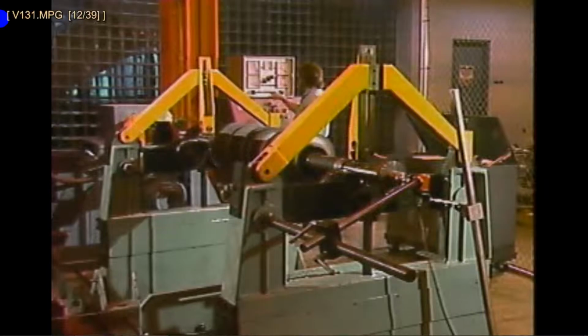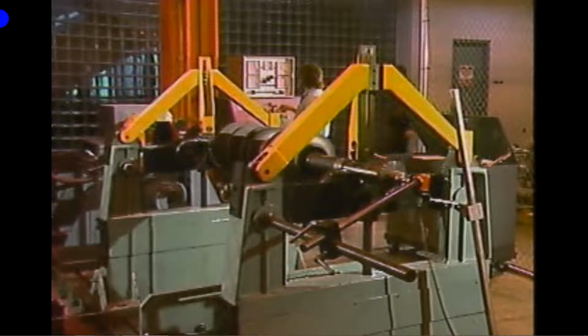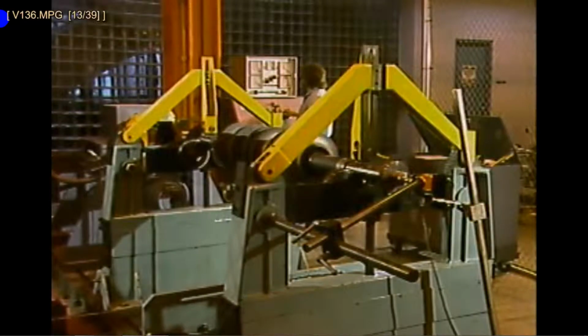One of the most common causes of vibration in rotating equipment is an imbalanced part. A rotating part becomes imbalanced when its weight is not properly centered on the axis on which it rotates. A rotating part could be imbalanced because of a manufacturing error, wear, or physical damage.